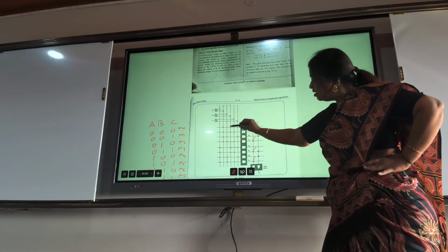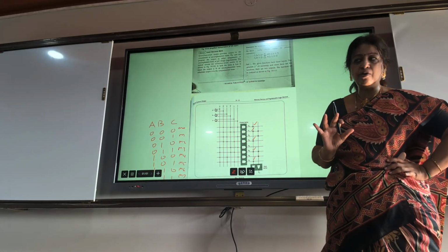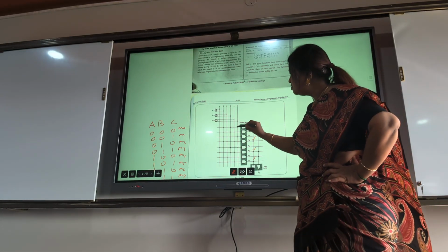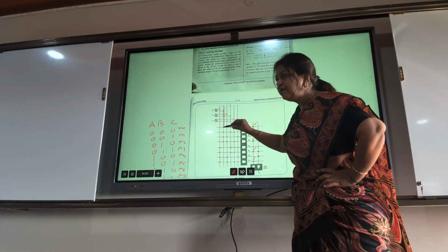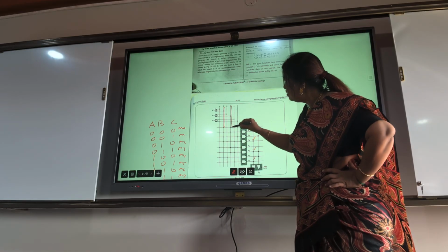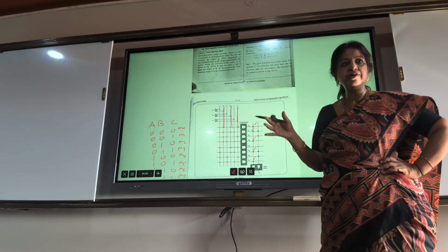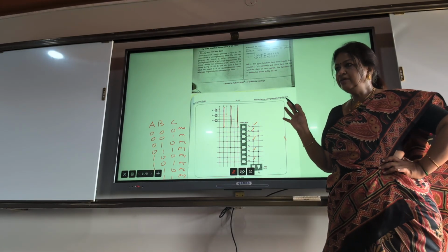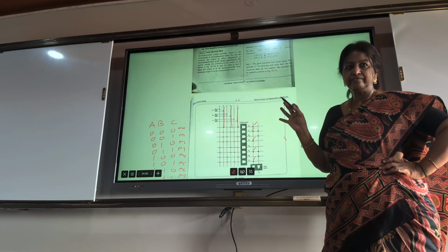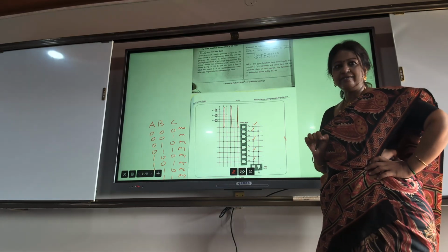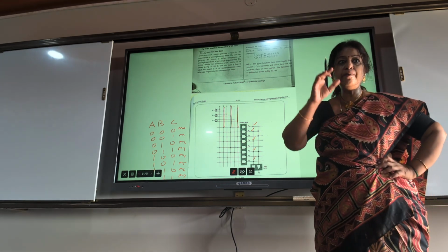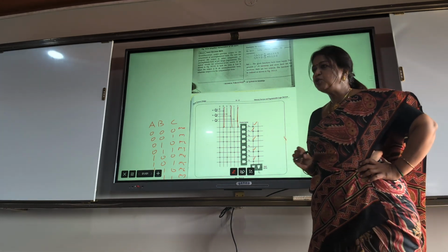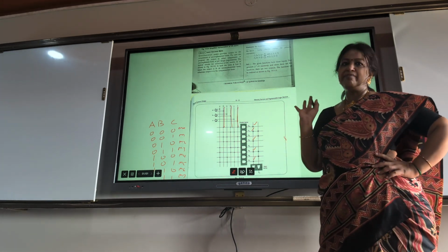Here the AND is already fixed. How have we connected 0, 0, 0? A bar, B bar, C bar. What you have to show in the diagram in the example: this should be a dot, this should be a cross mark. The cross mark shows that you can program. The dot shows that it is already programmed.